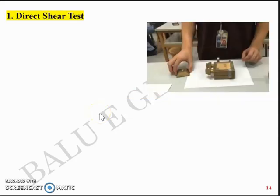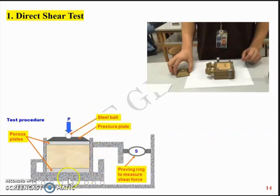In this particular video, we'll try to briefly discuss the various laboratory tests available now to arrive at the C and phi parameters. The first test is the direct shear test. In the direct shear test, you have a direct shear box which is usually 6 cm by 6 cm in plan and usually about 4 cm in depth.